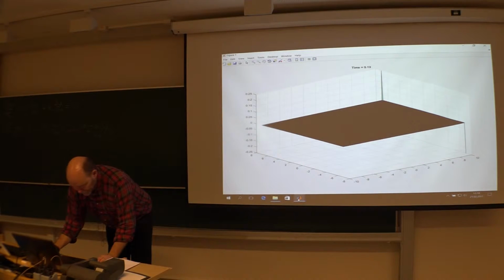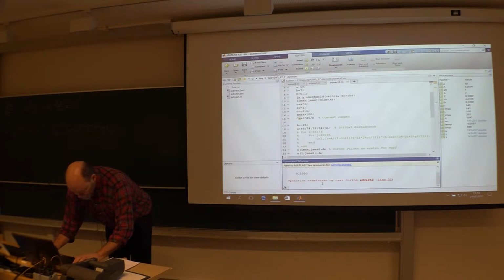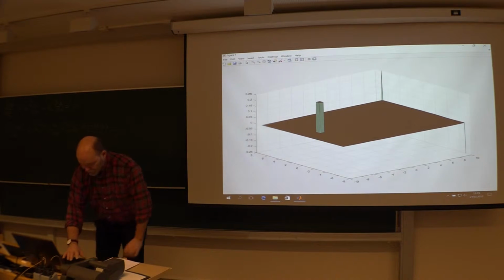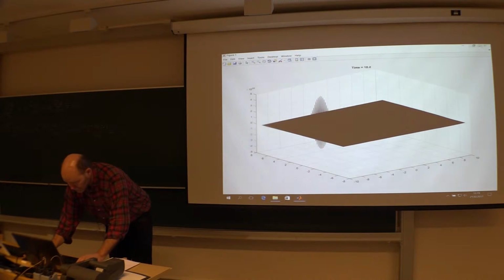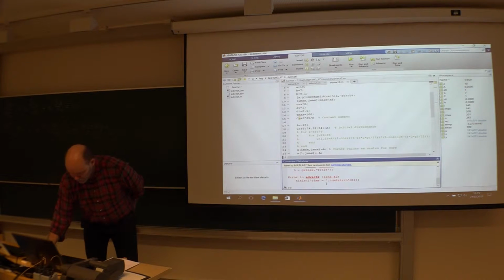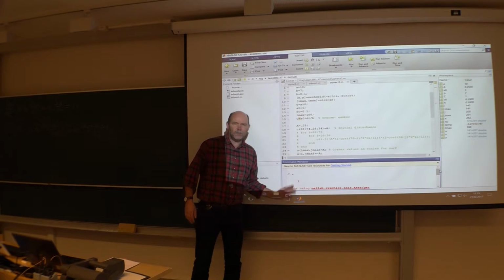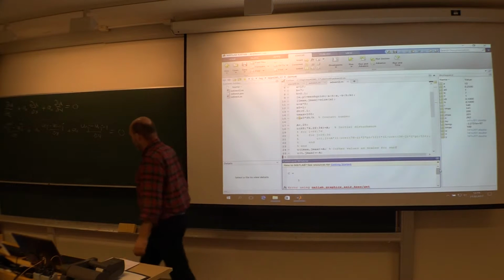Maybe a remedy here is actually to use a bigger time step. I had a very small one, 0.01, so let's multiply it by 10. It's still running down here. Bigger time step. No, that was a very bad idea. How big a time step can I use? The Courant number, as you can see down here, I printed out. Courant number is 1. Shouldn't that be allowed? What's the stability criterion?